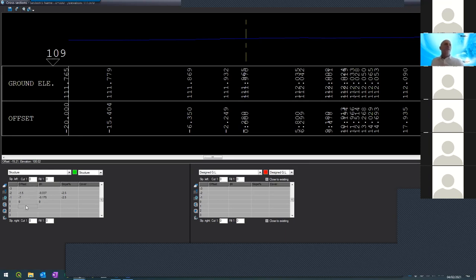And the same, now I'm going to the right. Again, 7 meters because it's to the right. And the slope is minus 2.5 because it's a camber. 1.5 meter, minus 2.5 for a camber. That's it. This is my template. Again, starting at 0, 0, which is the crown level, the center line level, going 7 meters to the right and 2.5%, 1.5 meter additional, 2.5%, then to the left, 7 meter, 2.5, 1.5 meter. Cover.